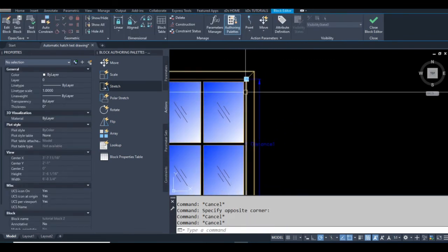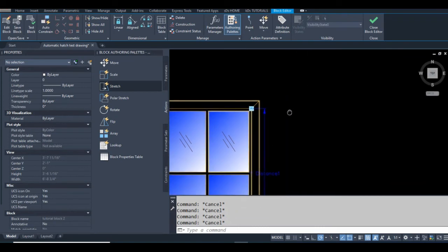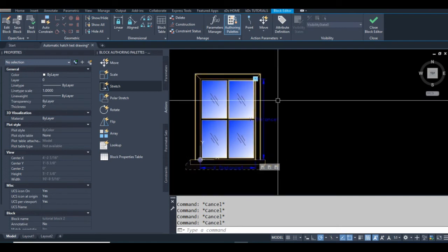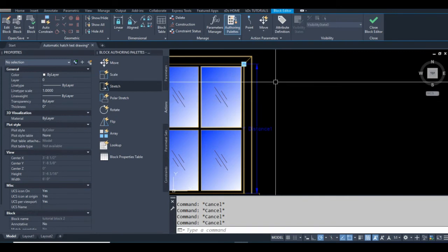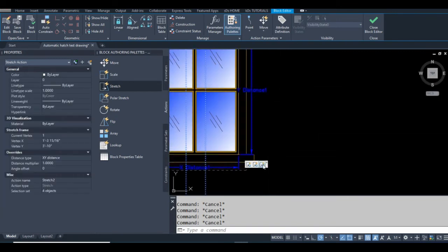But if you just manipulate the boundary, the hatch will follow that boundary almost all the time. There's exceptions to that, but if you're not using constraints, it's going to follow the boundary. So sometimes not selecting the hatch will make this more stable than selecting it.